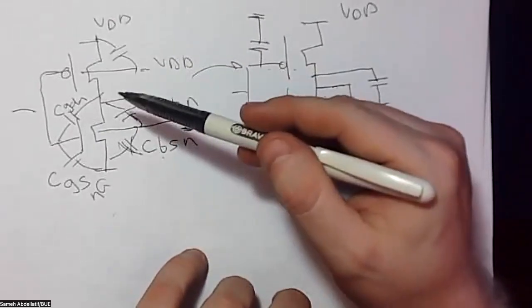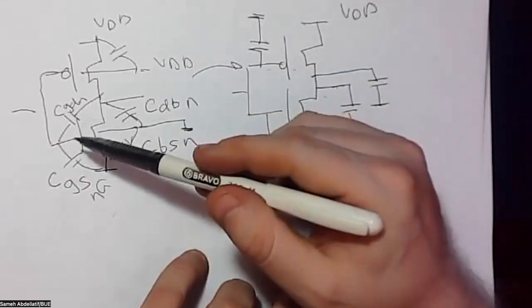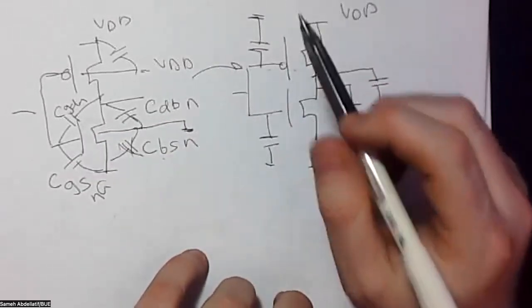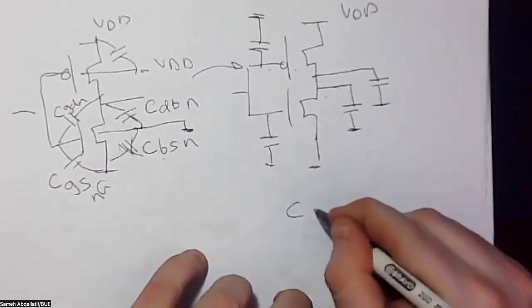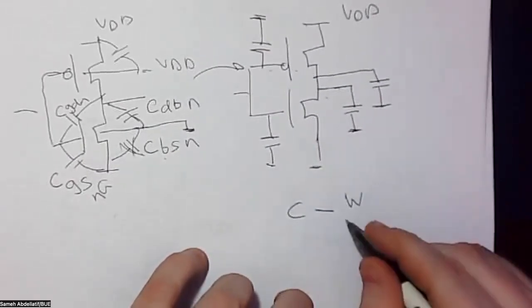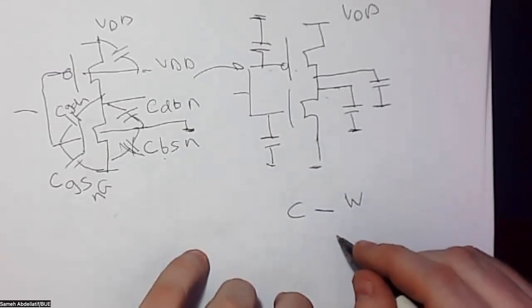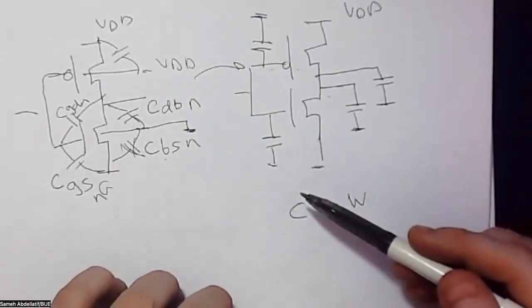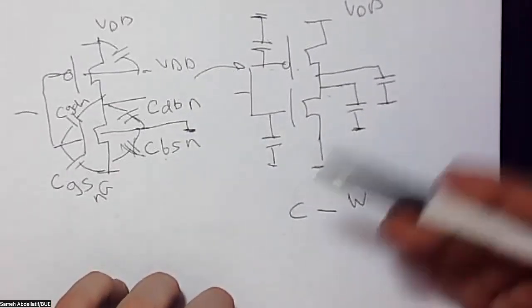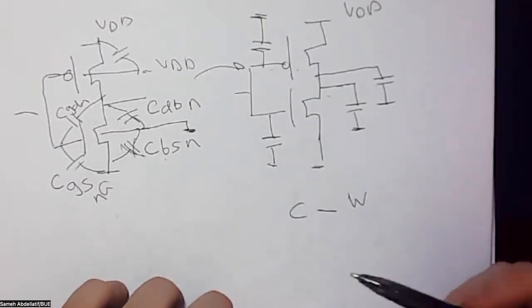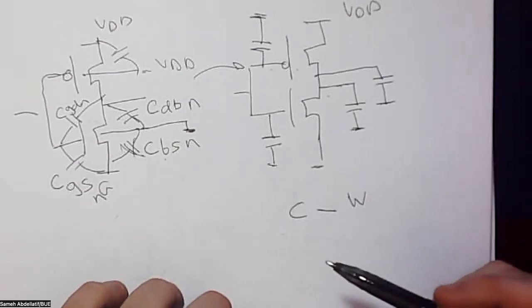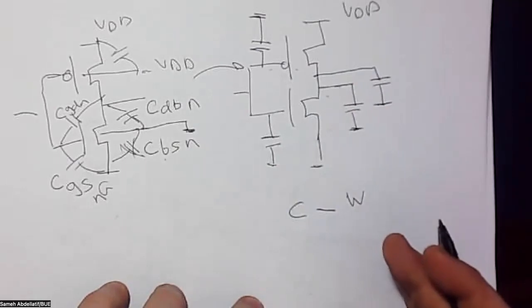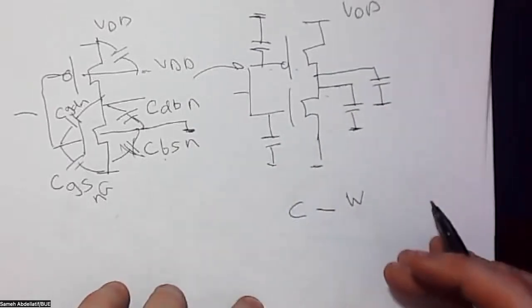I mean, it's not whether it's between the gate and the drain, or between the gate and the source, and so on. The main factor affecting the capacitance is what we can call the W, or the channel width. If you return to the basic understanding of capacitance from a CMOS technology or wafer cross-sectional point of view, you can understand that capacitances are mainly due to the vertical process in a MOSFET, not a horizontal one.